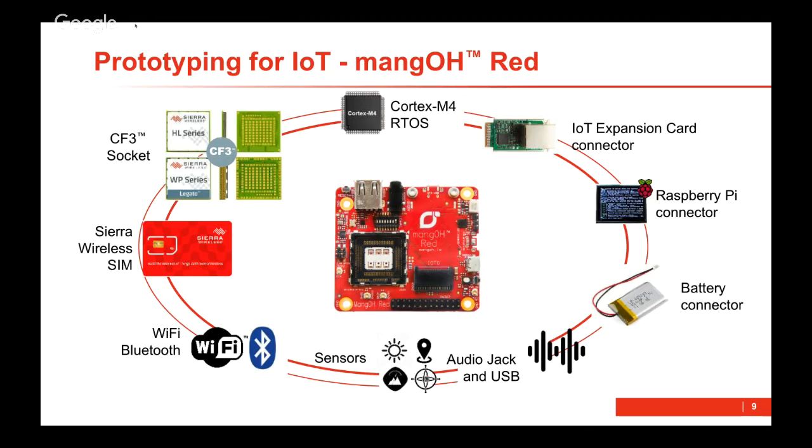This platform can run on a DC power supply of 5 volts input. It can also run on a battery. We provide, and we are about to just release it this week, a battery API as well. So this API can be used to monitor the status of the battery. You can get alarms based on if the battery is exceeding a certain level or below a certain level, if there's a change in state. So for example, the battery is going from a fully charged mode to a discharged mode. So you get a lot of these alarms.